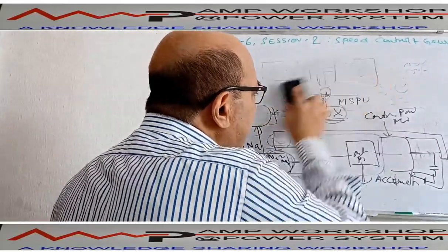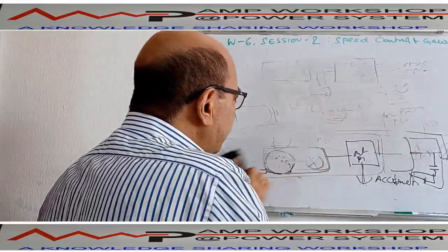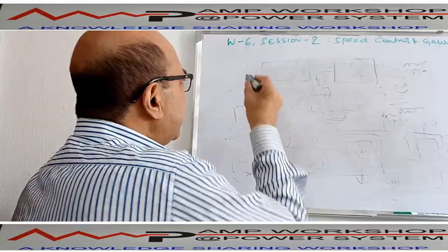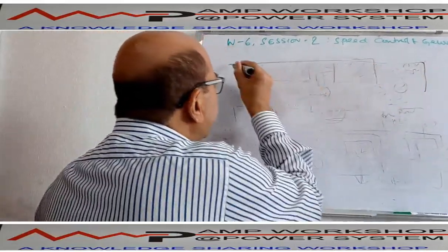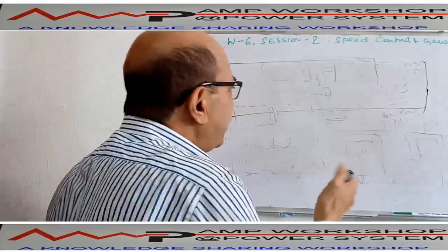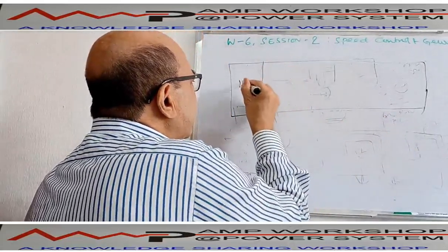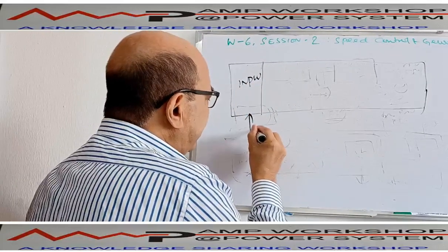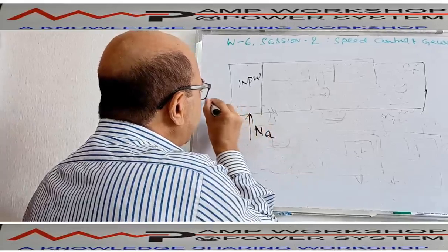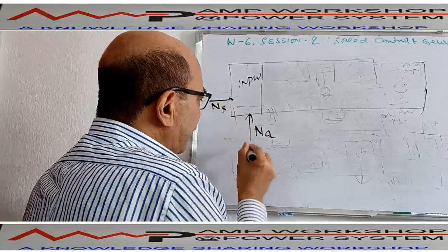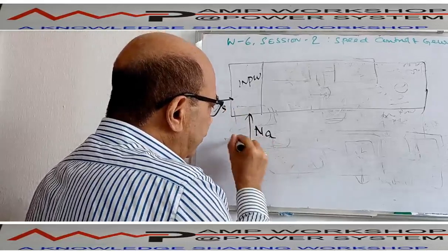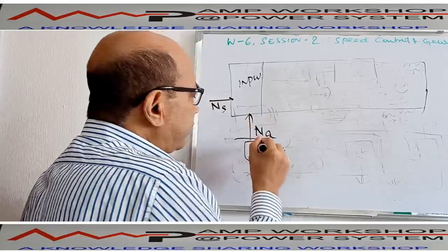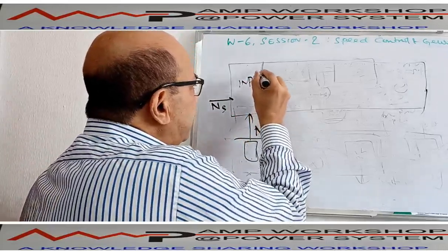If we look into the speed governor, which is controlling the speed, it has mainly 5 sections. If you divide the controller, you can see how many sections. One section is the input section, where the actual speed from the magnetic pickup is coming. That is the actual speed, and there is a reference speed. The magnetic pickup is on the turbine in the field, and this is in the control room. So this part is an input device.